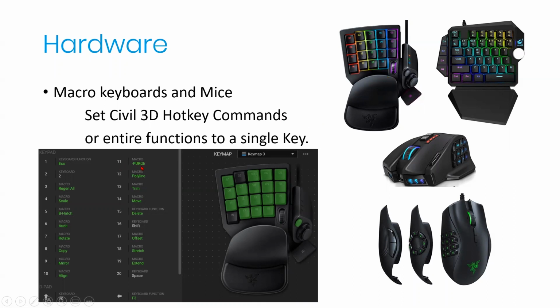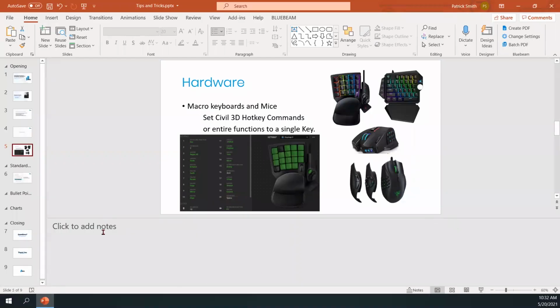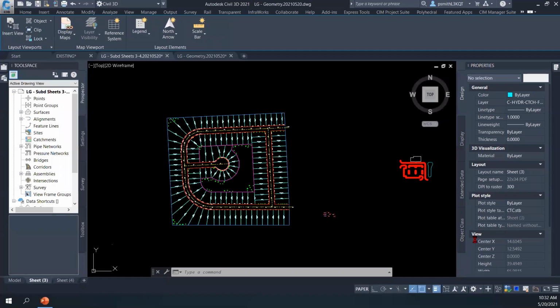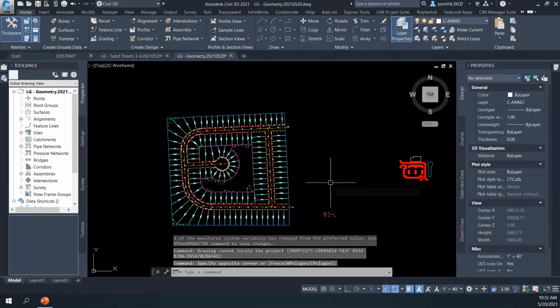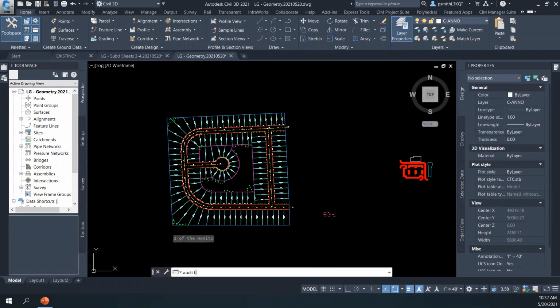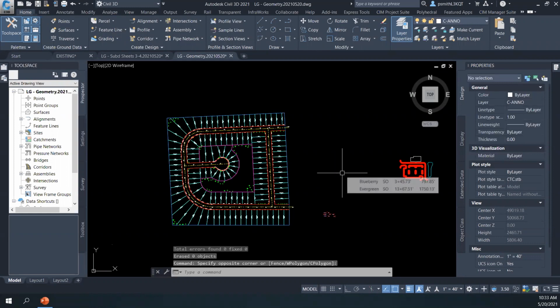And I just want to show you this. Purge and audit comes in real handy. I have it hooked up now, and I'll just show you exactly what it does. So right now I'm going to do my audit. It just types in audit, and it goes through without even touching anything. I just hit one key, and it runs through the whole audit scheme. All right. Just like so. Now I'm going to use my minus purge to purge out the reg apps.